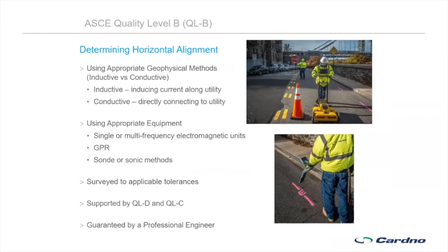Then the next aspect really is the meat and potatoes of subsurface geoengineering, which is the actual geophysical locating of facilities, using appropriate equipment, using electromagnetics, using ground penetrating radar, using sonic methods, to then actually get a true physical understanding of what's going on underground from an above ground scenario.